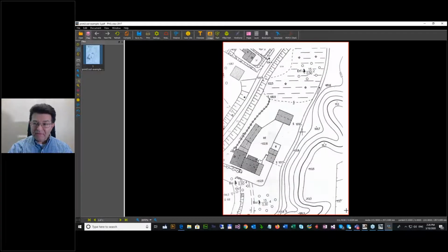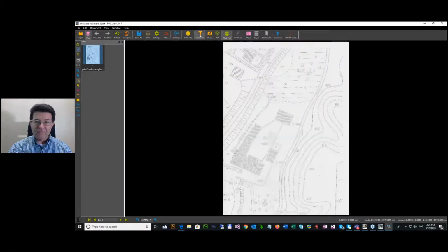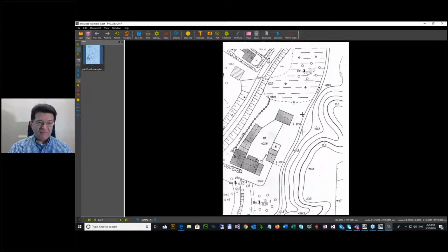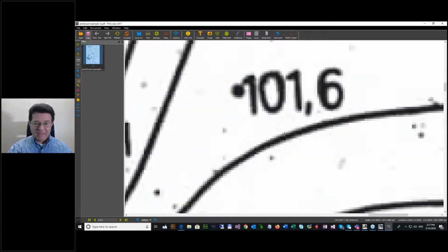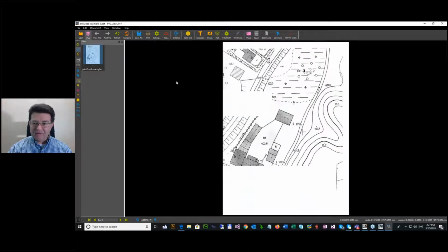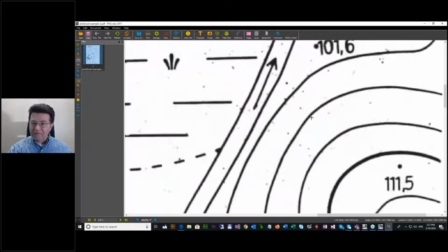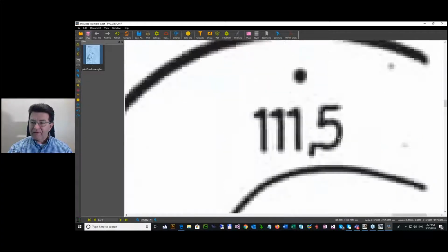Can you see the border here? This is the border of the image. No path, no fill path. What is it? This is not a real PDF file. This is normally only a raster picture in a PDF frame. Somebody scanned it, you see, it's a JPEG, a dirty piece of paper, and put it here as a raster picture.